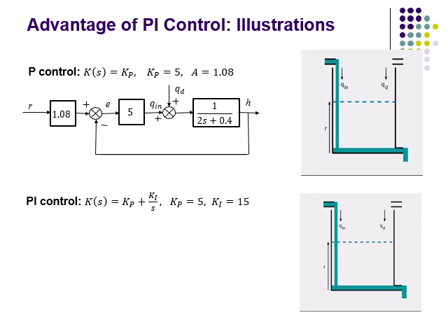Initially the height of water is 0, and then you see that the height increases to match R, but then a short time later we have some extra flow, so Qd becomes non-zero, and the effect of Qd is to create an additional flow rate into the tank. The controller doesn't actually know anything about the additional flow coming into the tank, and so the height of fluid then increases and we end up with a steady state error.